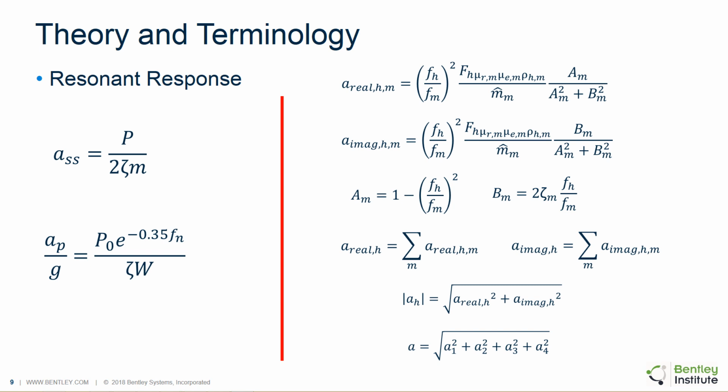And then we basically combine the results. So we sum the results down there near the bottom for each mode. You can see the summation here, where we're looking at the summation for each mode for an individual harmonic. So we sum those together to get a harmonic load. So we'll have 4 of those altogether because we're using the first, second, third, and fourth harmonic calculations.